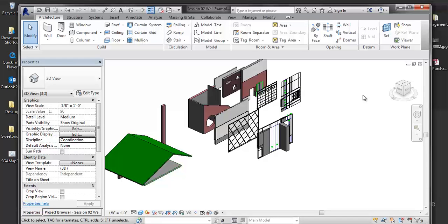The nice thing about these reference planes, as long as they're named, is that you can adjust that reference point and control types of a lot of models that way. But again, too many reference planes in the model starts to get a little crazy, and you get hundreds of different controlling geometry lines in the model, and they're overly complex. So a lot of times when I start, I'll just say level 2 to level 3, negative 12-inch top offset, and then top slabs.